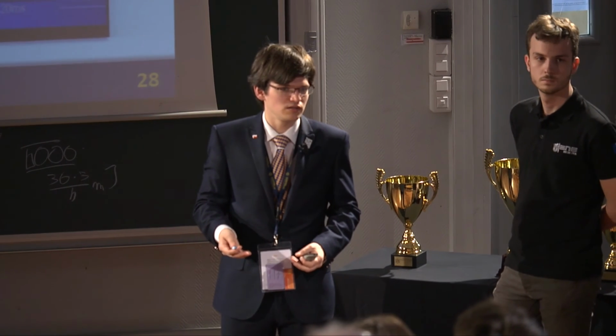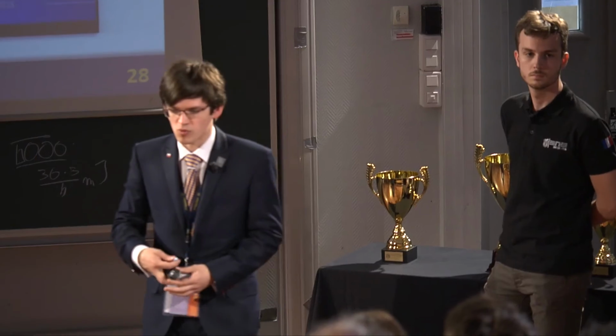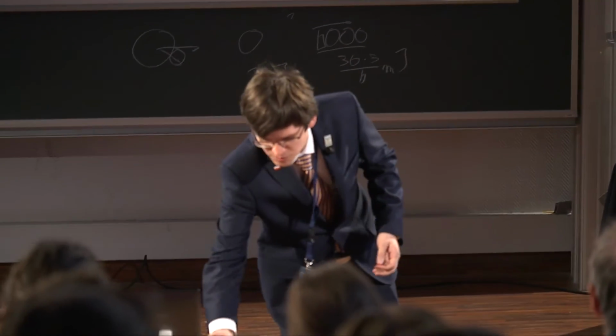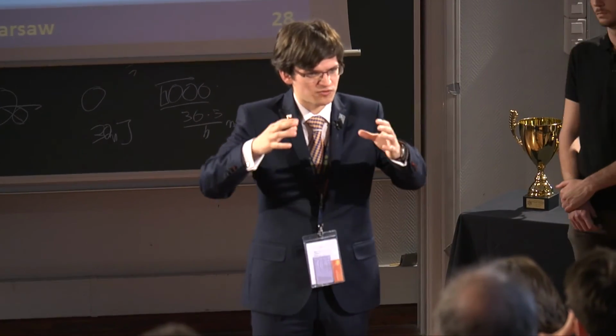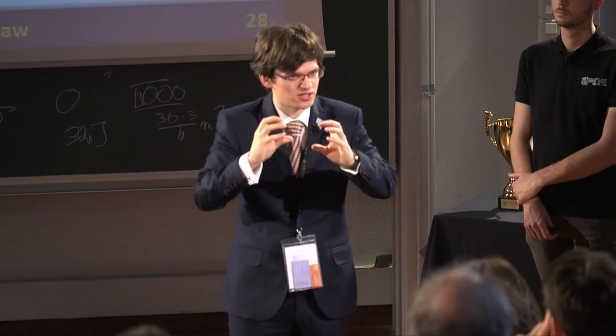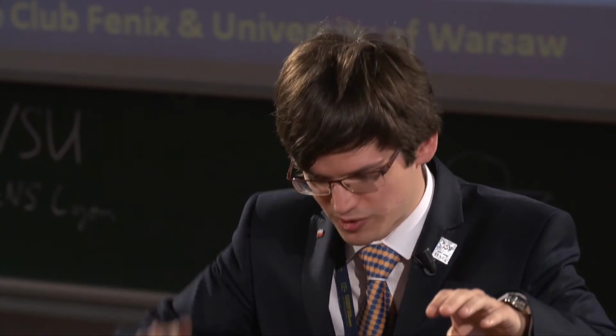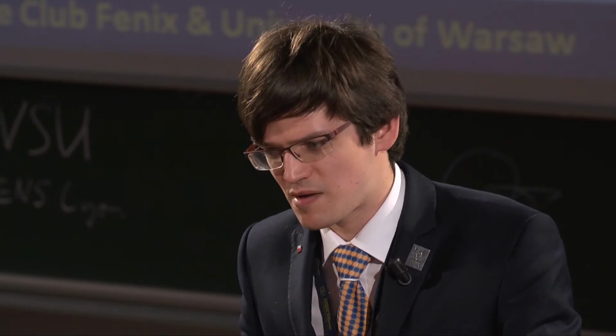Where does the dissipation come from? Dominantly, you have the dissipation because the material is deformed, and there's internal motion of particles. When you deform the material, the energy also dissipates. Like if you have a blade and you make it vibrate, after some time it loses its vibration, partly due to air resistance, but also due to the internal strains and stress. When you move, the molecules move between each other, and this causes energy to dissipate into heat.